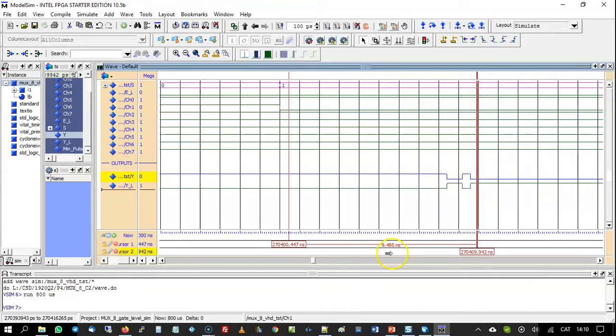It takes 9.5 nanoseconds to get the final output. So this is the measurement for this second. You may say that is about 9.5. The signal first of all takes a long time to do something. It is like frozen. But then there is a switching here, and in the end it goes 0, and then it goes high again, and finally it goes to the final and permanent value.